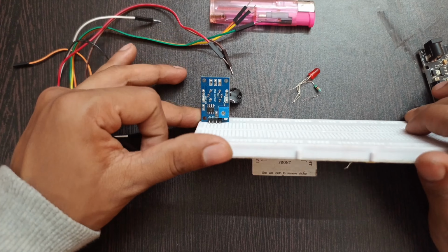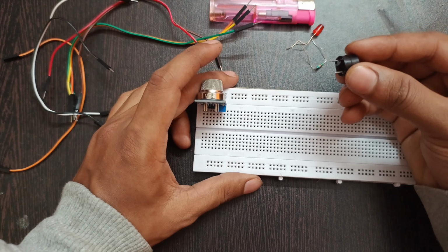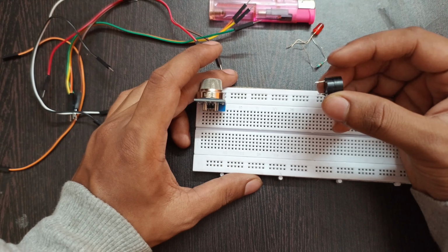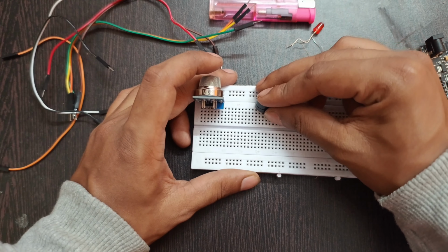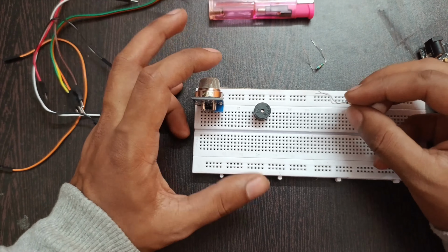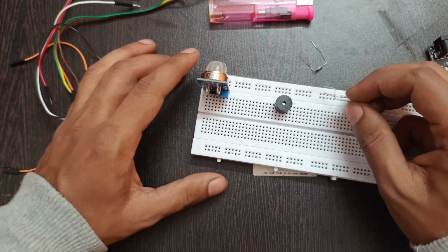We have connected a sensor. Of buzzer, we are going to use the positive one for digital pin, the negative one for ground. So maintain some distance with each components. It will be more easier for you to recognize any failures in connection.